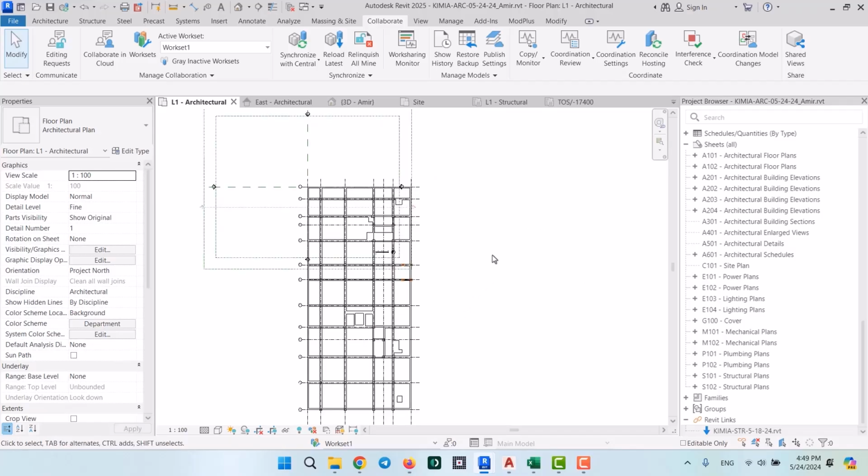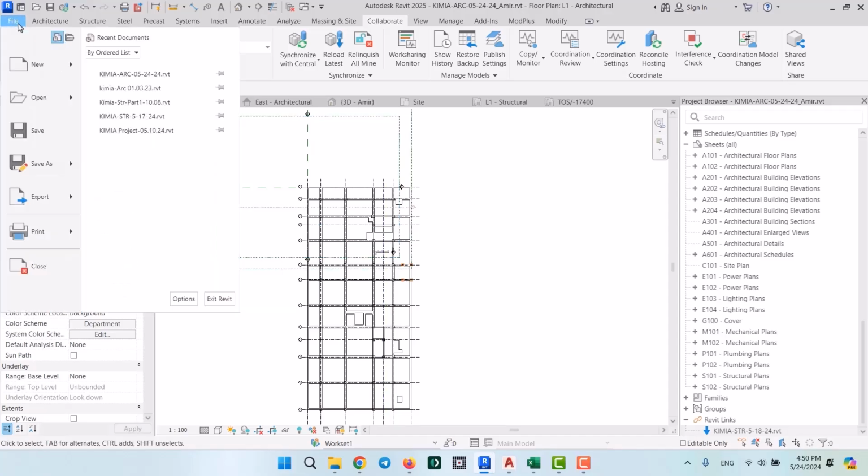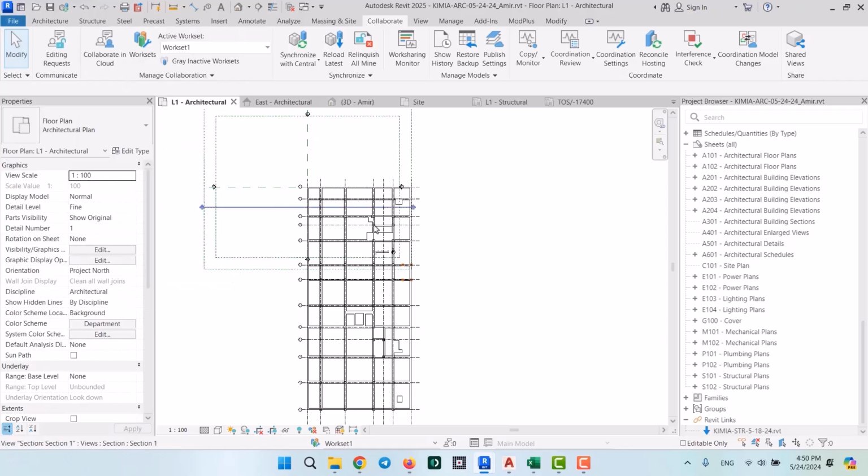You see, in all of our projects, we've got a view template. For example, for the measuring plans, we have one template, and another template for the flooring and another template for the elevations. In fact, we have a separate template for each series of documents, which you could go into and make your grids and levels invisible in there. That way you won't have to go into every single view, then to the Revit links to make the grids and levels invisible. And actually, I'm gonna give you a quick example to help you understand it better.